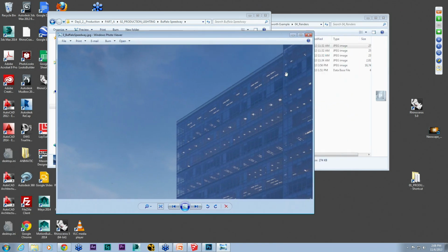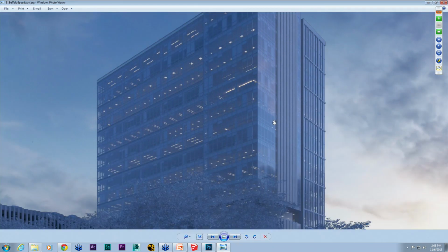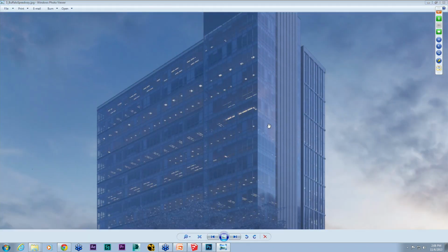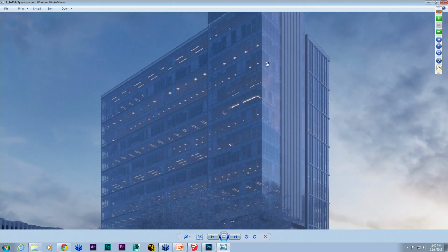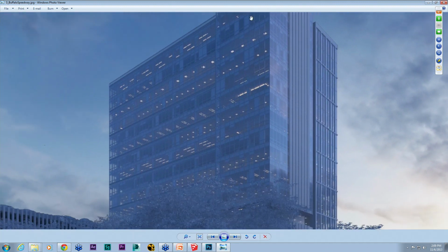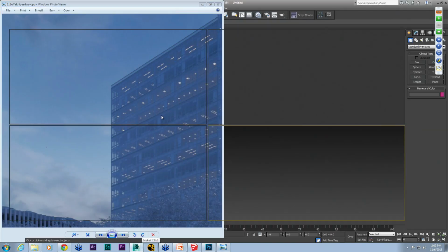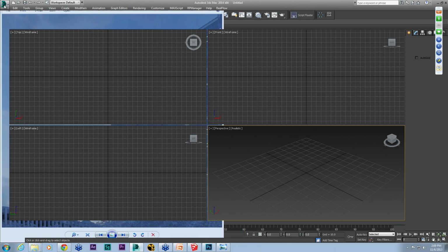So basically what it is, though, is it's a blend material and a multi-matte material, and I select a floor, and I'll change it to a different material ID, and then I'll have a single UVW map on it, which kind of fits all those together. And I'll try and get in there one more time to show you guys.